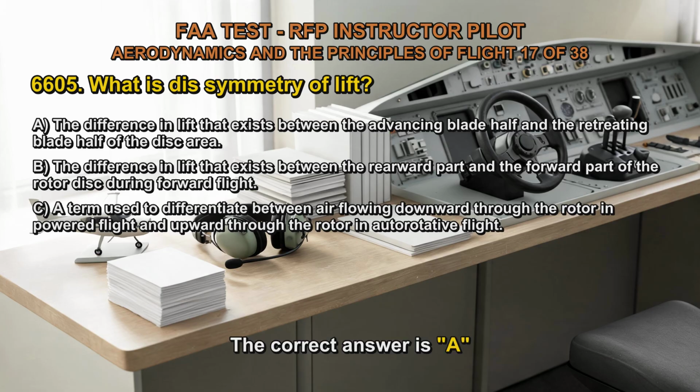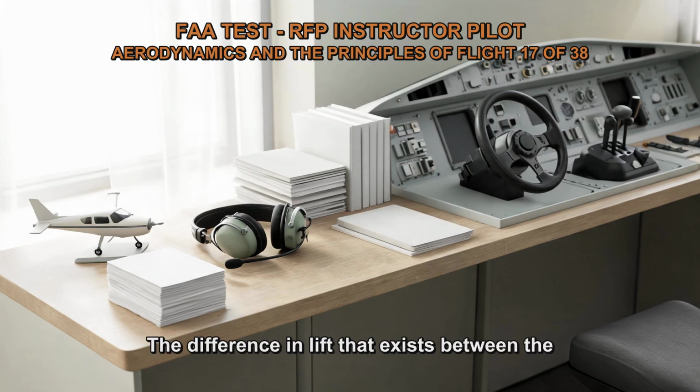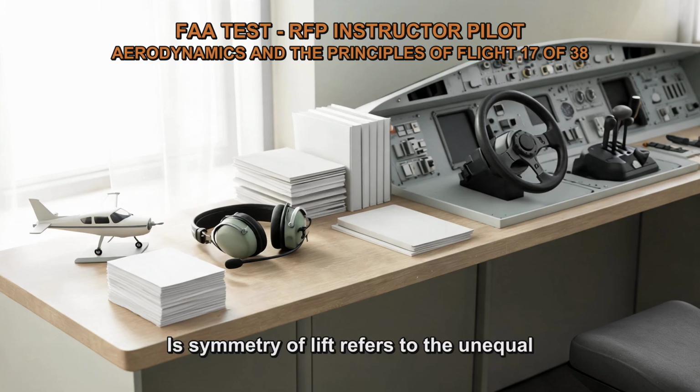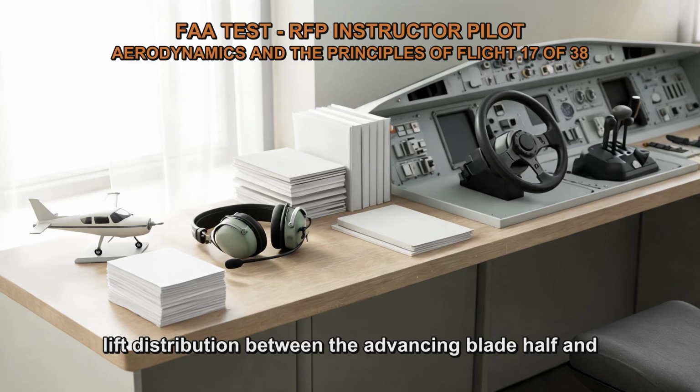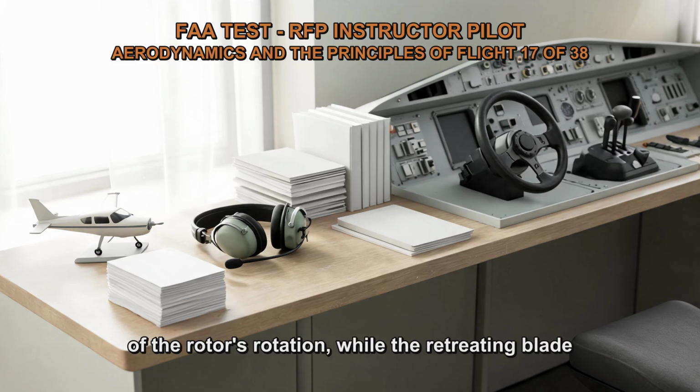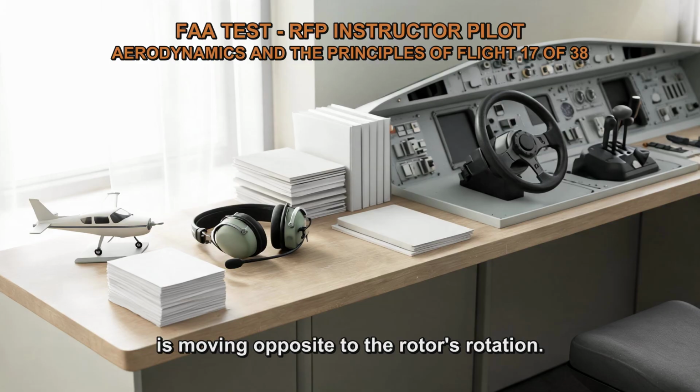The correct answer is A. The difference in lift that exists between the advancing blade half and the retreating blade half of the disk area. Dissymmetry of lift refers to the unequal lift distribution between the advancing blade half and the retreating blade half of the rotor disc. In a rotorcraft, the advancing blade is the blade that is moving in the direction of the rotor's rotation, while the retreating blade is moving opposite to the rotor's rotation.